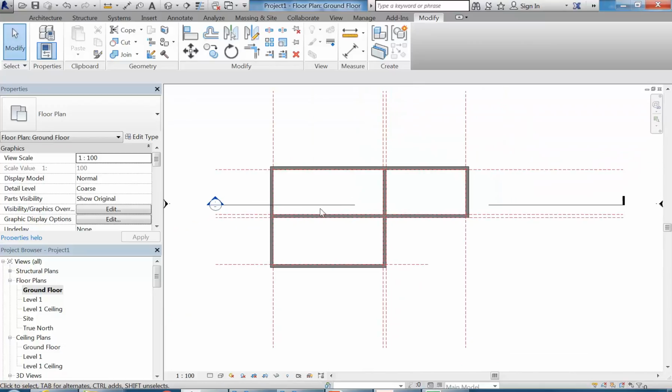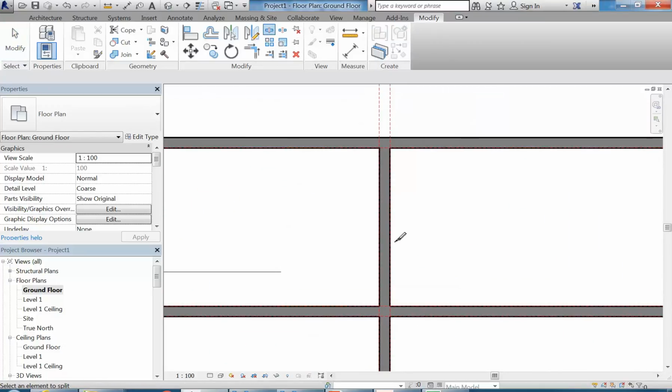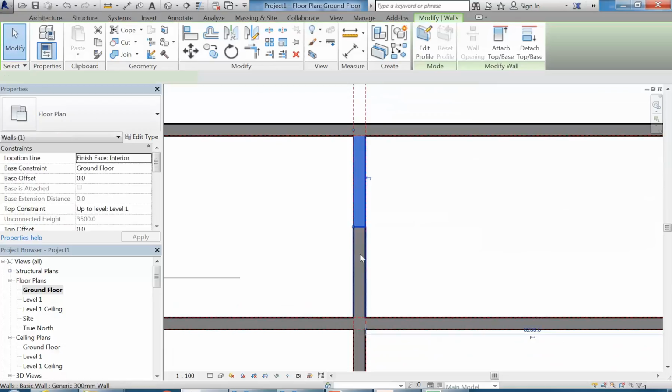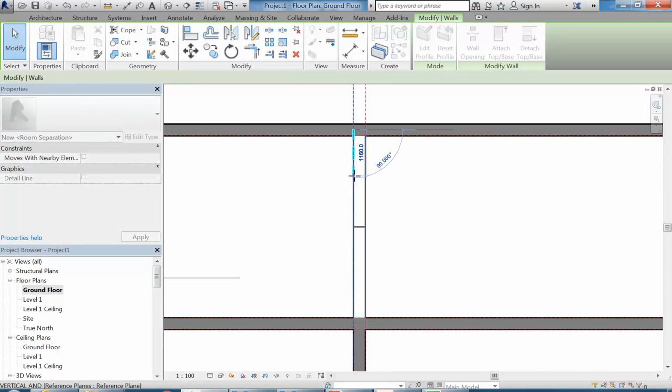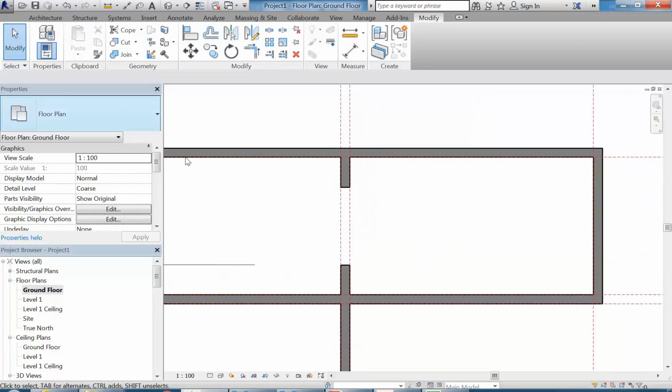no, I'll show you the better way, so we should do it the right way from the beginning. I was going to show you a quick way would be to use Split Element, and I'll break the wall. So I've broken it in the middle there, and then we've got 2 pieces again, and I can select one of those, and this time just drag that away. But can you think of any problems with that approach? If you make an opening like that? How are they in real life?